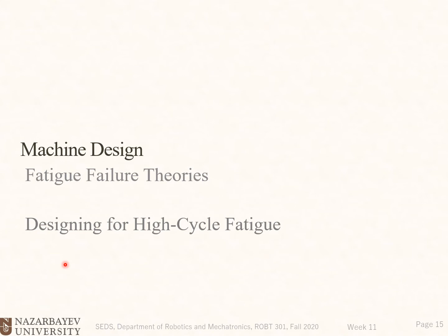As we did for static loads, we had von Mises theory and maximum shear stress theory, and those were for ductile materials, and for brittle materials we had Mohr theory. So we developed those theories for static cases, but we haven't developed any theory so far for fatigue loads, for dynamic loads.